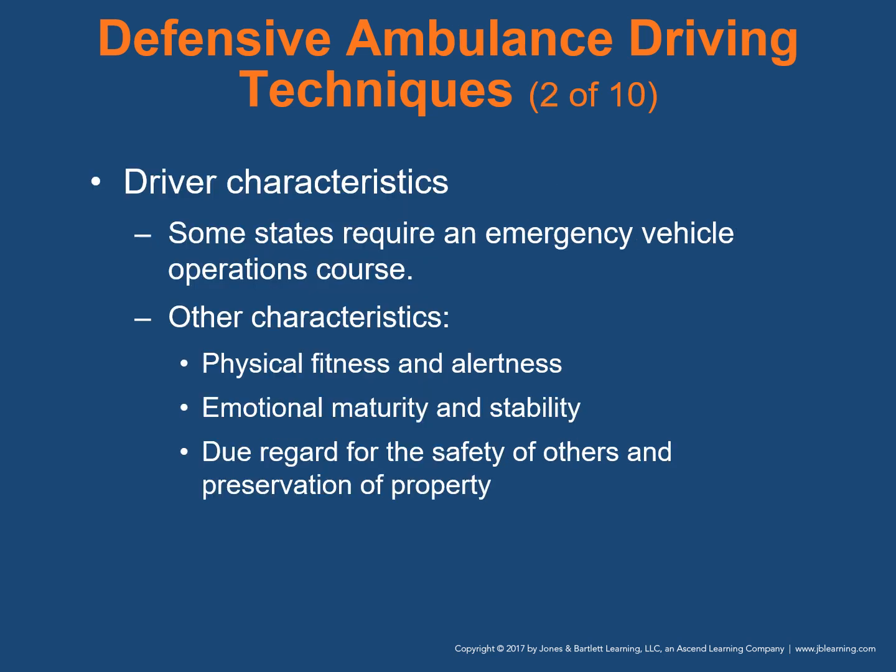With driver characteristics, some states require drivers to successfully complete an approved emergency vehicle operations course. That's what I was just referring to. Physical fitness and alertness are necessary to properly operate an emergency vehicle. You should not be driving if you take medications that can cause drowsiness or slow your reaction time, if you've been drinking alcohol, or if you've been working long shifts or multiple consecutive shifts.